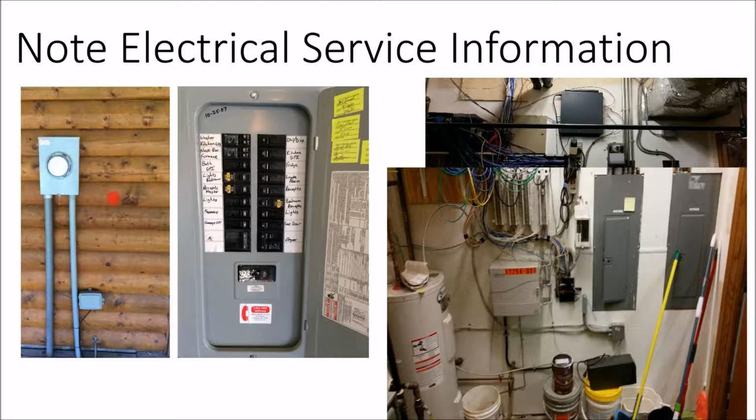And so you have to ask yourself, well, what's the cost of a junction box and a couple of tap connectors? That can be $50, maybe even if it's a metal box, maybe it's $100, versus taking this breaker out here and then putting in a double pole breaker slot with a sub panel, and then reinstalling that breaker, and then putting your solar breakers on the sub panel. If you don't have any space inside your main panel, it may be that a supply side connection is the way to go.